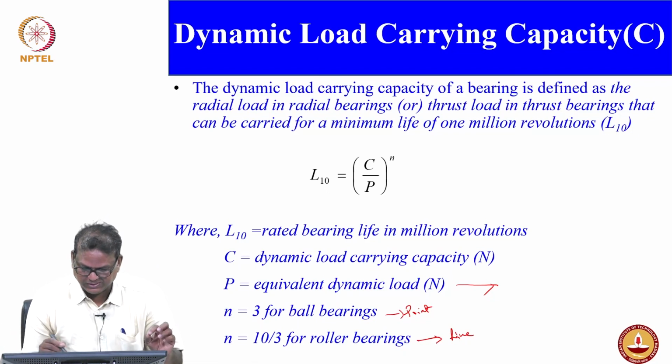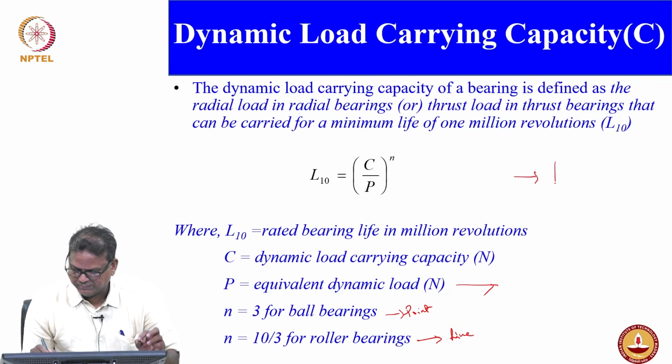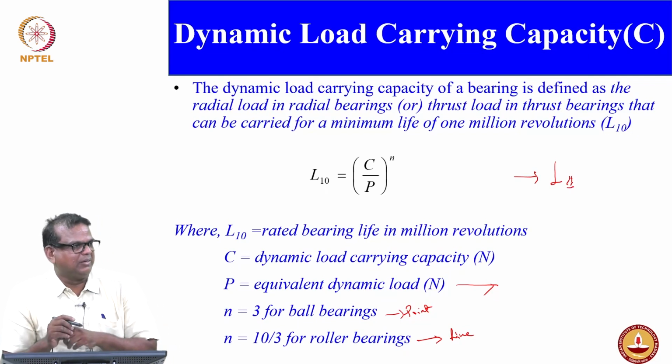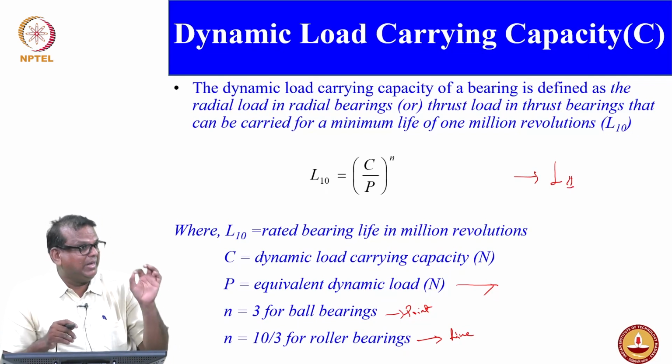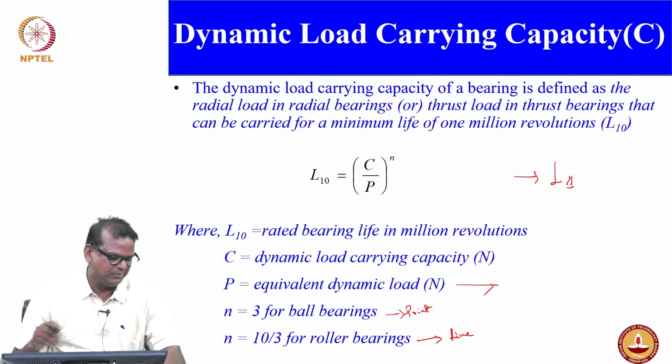For aircraft application, the quality of the bearing life is even more stringent. So, they will have what is called L1 life. That means 99% of bearings should complete 1 million cycles without showing evidence of pitting.